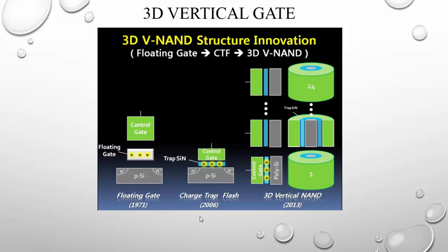3D NAND uses a charge trap because it's extremely difficult to create features like a floating gate, with sideways lithography working from the top down. A charge trap, when used to replace a floating gate, doesn't need to be patterned. Since the charge is on one bit, the charge in the trap will not leak through the insulating charge trap layer into the adjacent bit cell.